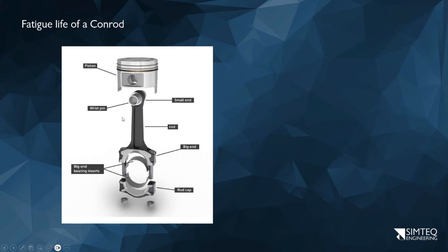Here's a very simple additional example that's kind of easier in some ways. Simply a conrod, and the stress level of the conrod depends on where in the cycle it currently is, but it's cyclically up and down. And if it's free spinning, there's a slight side load because it comes at an angle for certain point and there's acceleration sideways. But most of the load is in the direction of the conrod. So kind of a buckling load, almost tensile compressive.